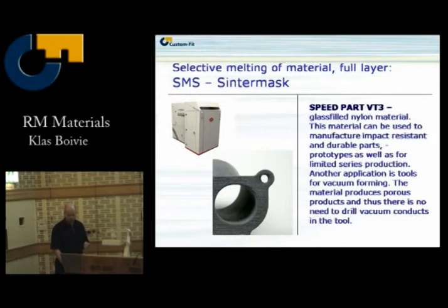I could add that due to their process, they also have a more serious melting of material parts, so they claim to get a little bit better material properties than common SLS. On the other hand, they have a little bit coarser surface, so they have to be worked a little bit afterwards. Otherwise, they have a couple of nice features. They're scoped for that process, at least I have.